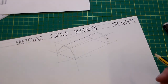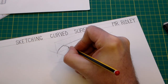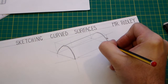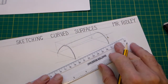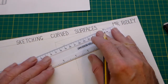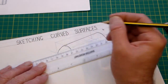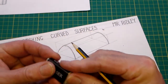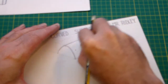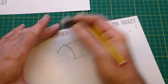Then once we've got that shape, we can use a pencil to line the shape in. Obviously we don't need the detail from behind. We can line in our detail along here. And then using our eraser we can just clean up any detail that we don't need now. These lines are construction lines and should be drawn as lightly as possible.